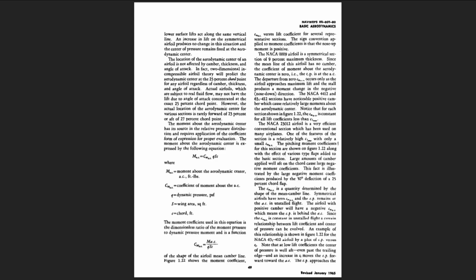The location of the aerodynamic center of an airfoil is not affected by camber, thickness, and angle of attack. In fact, two-dimensional incompressible airfoil theory will predict the aerodynamic center at the 25% chord point for any airfoil regardless of camber, thickness, and angle of attack. Actual airfoils, which are subject to real fluid flow, may not have the lift due to angle of attack concentrated at the exact 25% chord point.